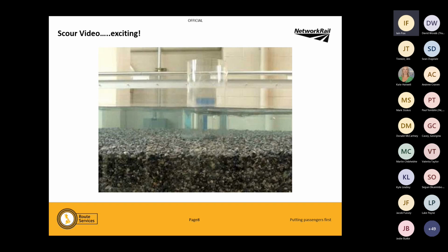So we've increased it from 27 to 35. I'm just going to pause it there. Now you can start to see some little depressions in the water, some little bits of turbulence, but there's still not a lot going on at the base of that structure. We're going to increase it now to 42 litres a second. Now we've definitely got some turbulent flow.